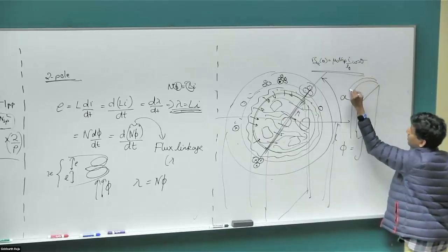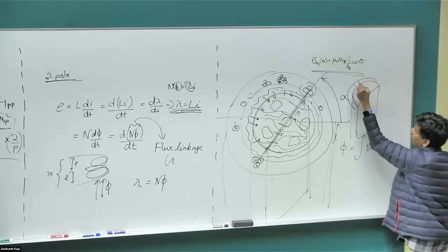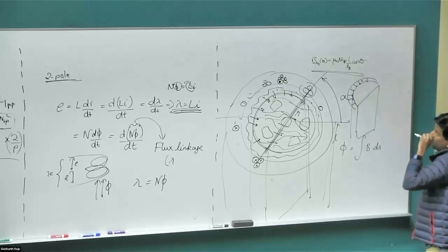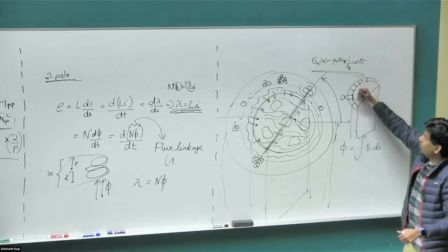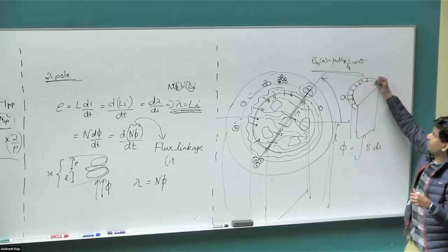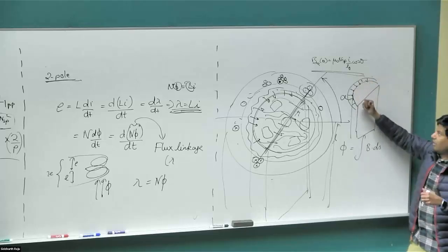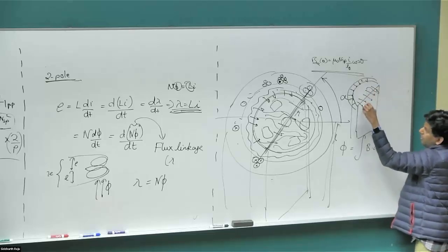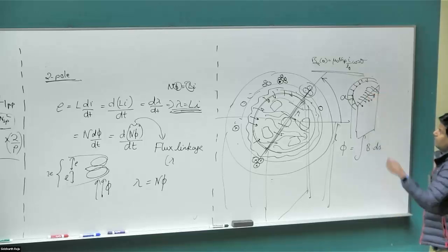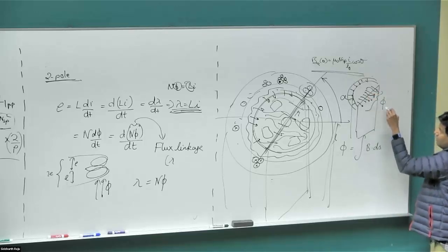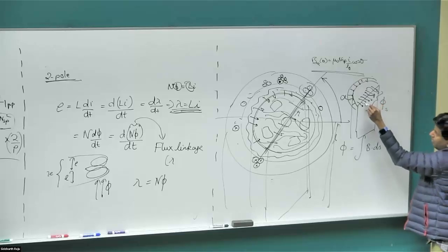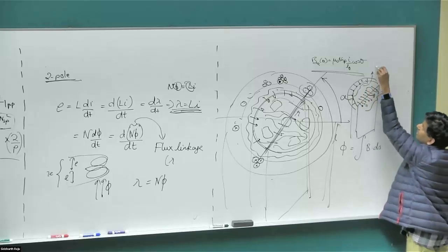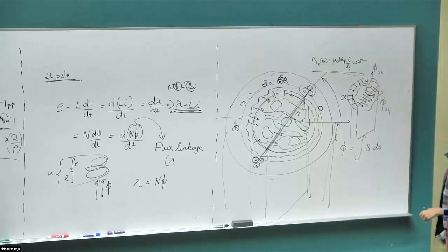and this is basically the air gap. So I know the B field at every single point in the air gap, and that's the formula that I have there. And I can integrate the B field over the surface area and that will give you the flux entering this surface area. And that flux must be exactly the same as whatever the flux is leaving out of the surface area. However, the shape of it doesn't matter. Right? So the total flux that's leaving here, let's call this surface 1, must be the same as the total flux entering this side, the flux of surface 2.